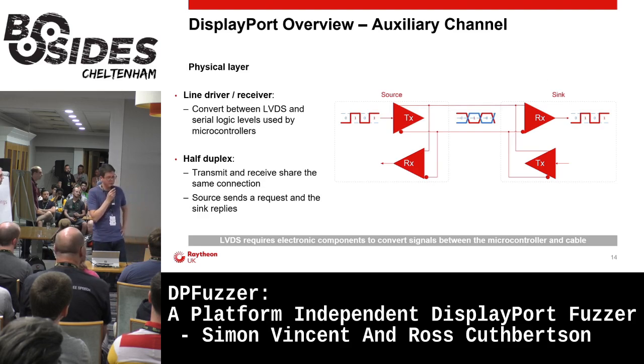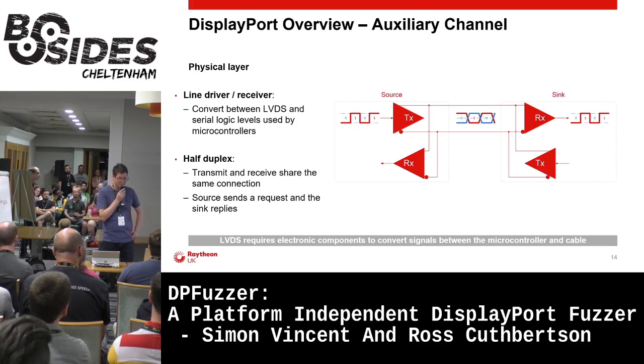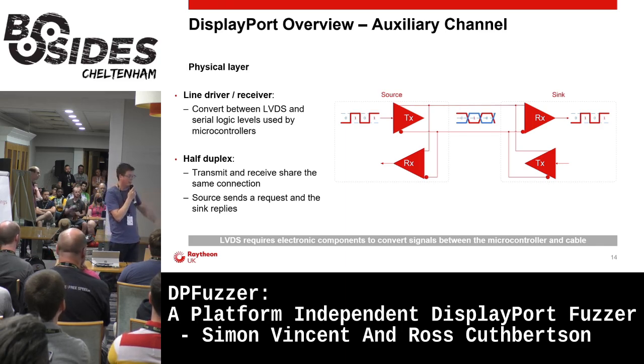So we need some electronics to convert between the single and differential signals, and this is called a line driver, and it's represented in this image by the triangles. So serial signals from your computer will be converted to differential signals as found on the actual cable itself, and then that's converted back again on the display side.